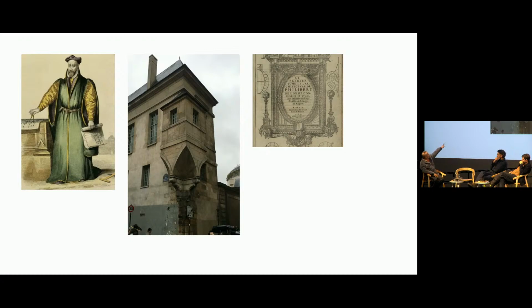Okay, so this squinch that is just this square tower in this angle, 100 years or 200 years earlier would have been a succession of corbels, okay, thick corbels on top of each other. But here we said no. I really want to be as efficient as possible with the stone I've got. It's coming in 200 mil thick, okay, and I need to extract as much as possible of that stone. And to extract as much as possible of that stone, you need to be a keen stereotomician